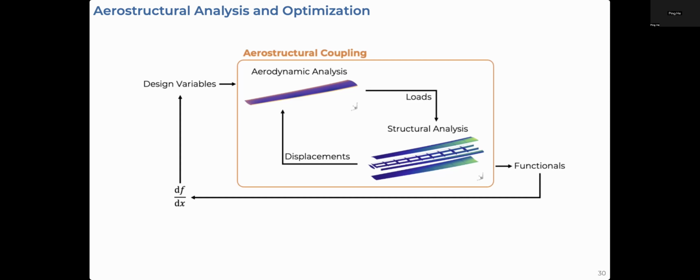The optimization problem we'll look at is multi-point through our different scenarios, but overall we're trying to minimize propeller cruise thrust with respect to a maneuver angle of attack, the wing chord, twist, sweep, and shape distributions, the tail deflection of the elevator, and the structural thicknesses of the panels in the tail and the wing. The propeller locations are tracked to make sure they stay a constant distance from the wing, and a cruise maneuver and thrust. So we have 364 design variables.